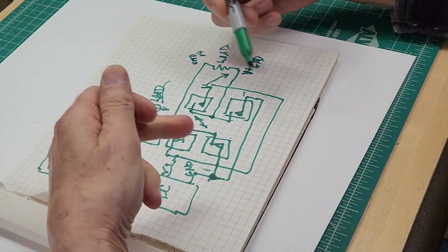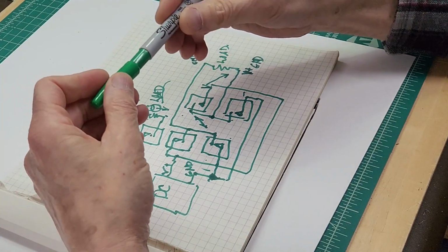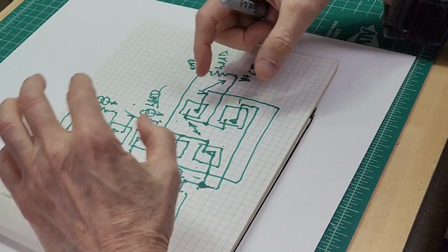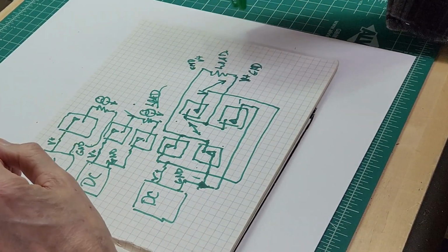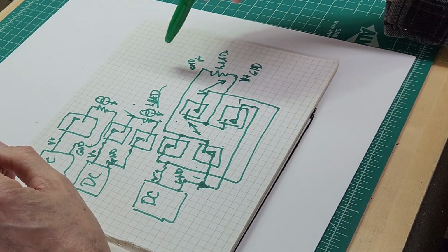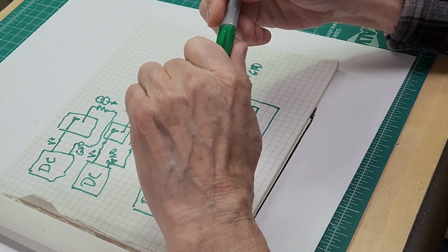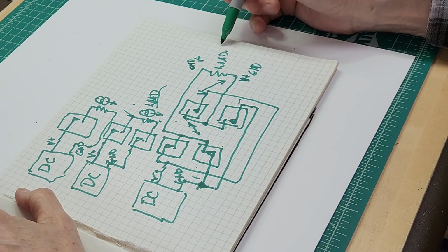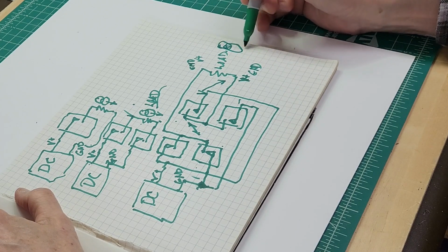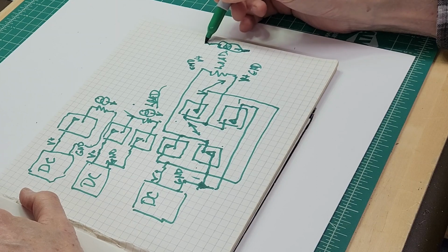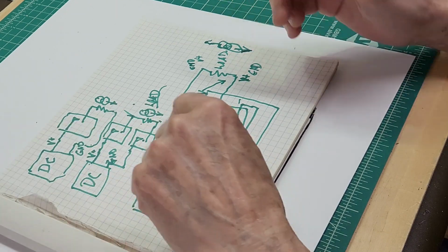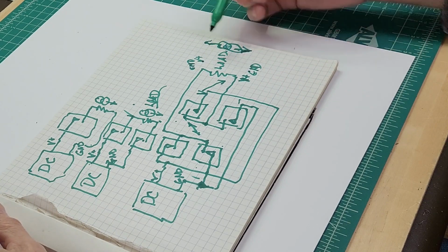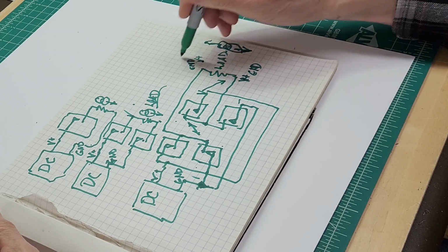So by adding these simple switches and closing them in the right sequence, I can create an alternating application of either voltage or ground on the load. And by doing that in a sequential fashion, the current that we were creating now flows in both directions. It's alternating. It depends on the switch setting. So if V plus is here, the current is going down through the load.